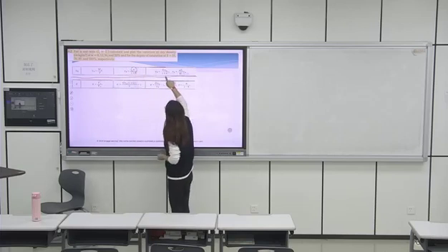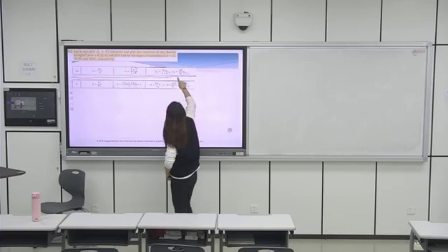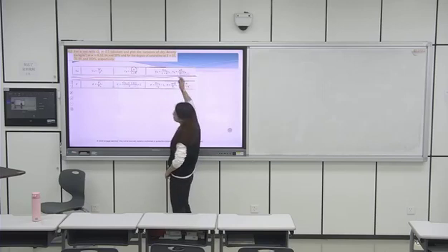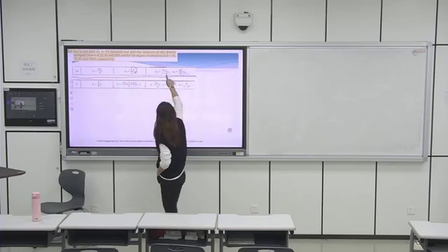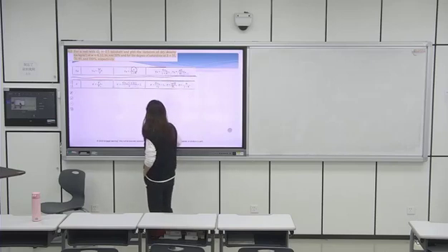Here, we know Gs, but you don't know the void ratio, so it's difficult to use this. But for here, we know water content and degree of saturation, and we have no idea of porosity n. So for these two, we can try to find the void ratio with this equation.